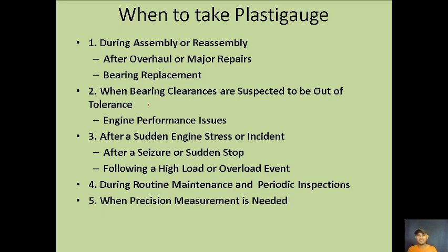So when to take plastic gauge? First, during assembly or reassembly, after overhaul or major repairs or bearing replacement. Second, when bearing clearances are suspected to be out of tolerance, like with engine performance issues. Number 3, after a sudden engine stress or incident, after a seizure or sudden stop, following a high load or overload event, or in case of an accident like grounding and collision. You can also take plastic gauge as an additional measure to your crankshaft deflection during routine maintenance and periodic inspection, and when precision measurement is needed.